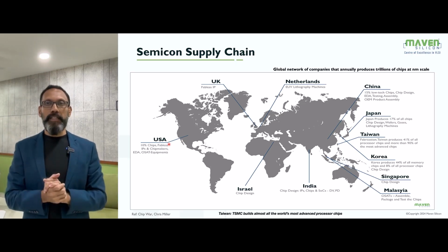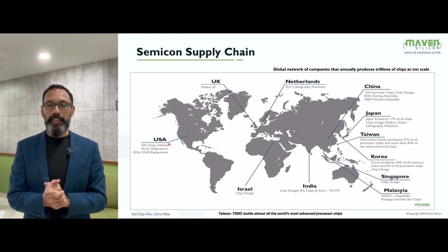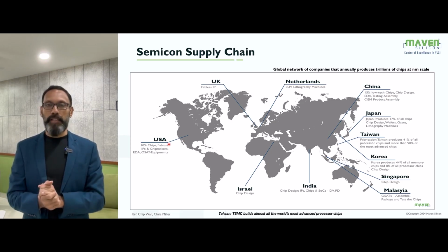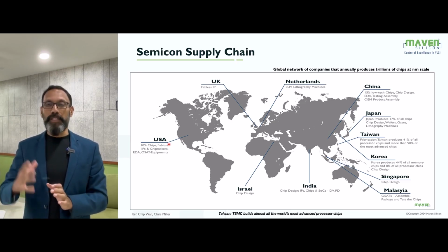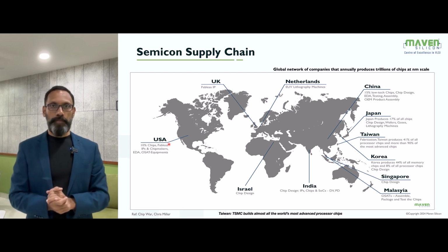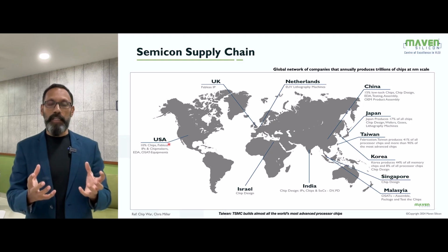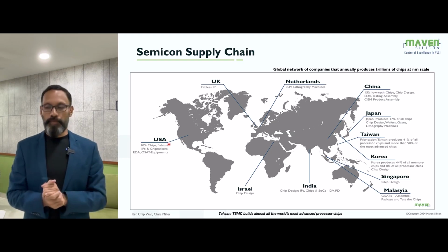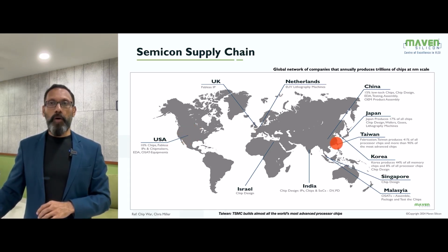As part of the physical design, we follow various steps: floor planning, place and route, static timing analysis, clock tree synthesis, physical verification, and then finally layout versus schematic. And that's how we generate the routed netlist. So at Apple, they basically generate the routed netlist. It's called GDSII. And they outsource the chip fabrication to a company called TSMC, which is based out of Taiwan.